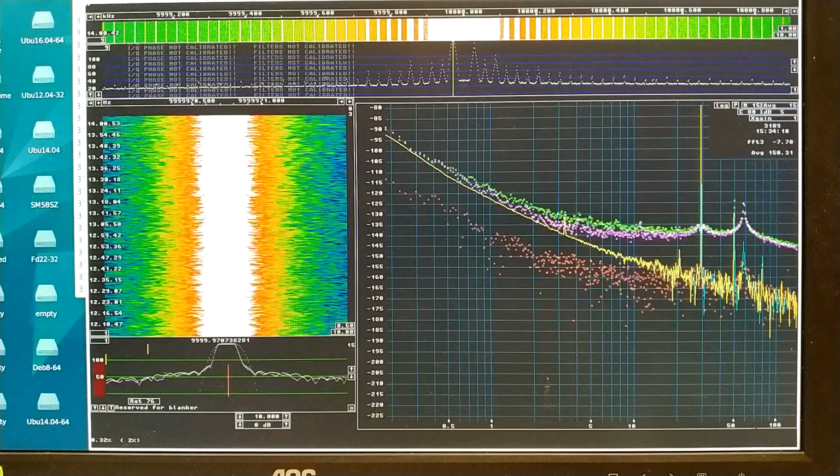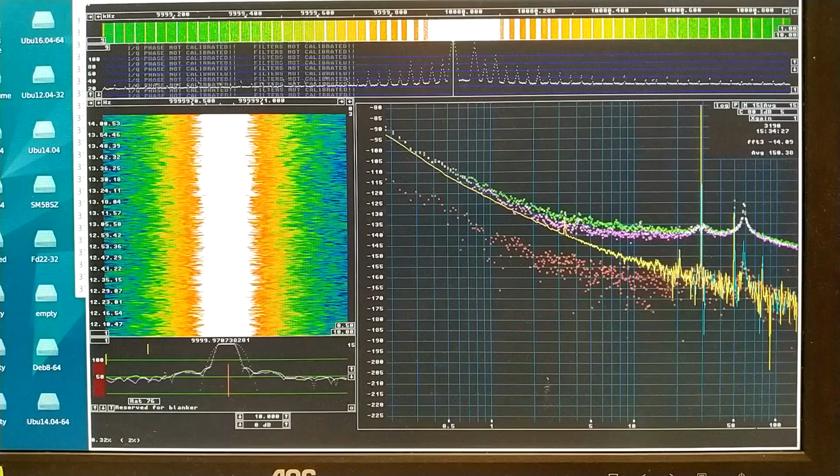I'm using Linrad to measure phase noise at close range. As you can see on this screen, it has been running for 15.5 hours, so statistics is very good. Now I have enabled network, so the raw data is sent and is available on the network.